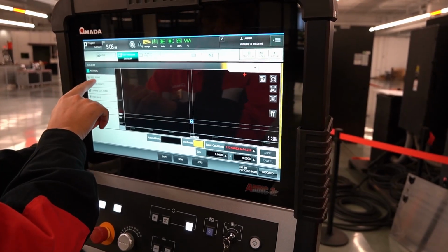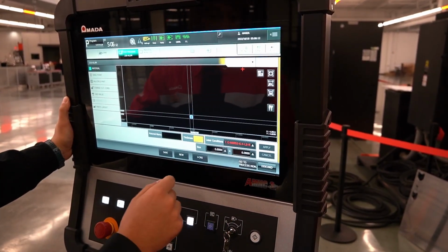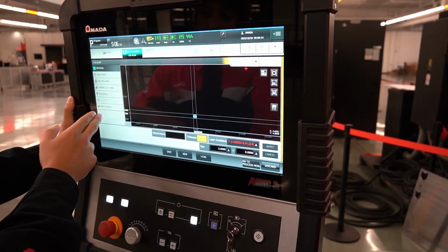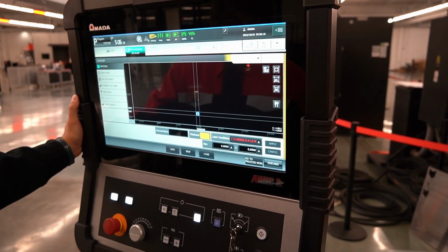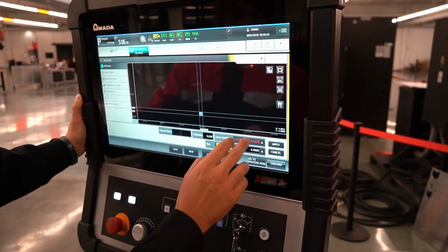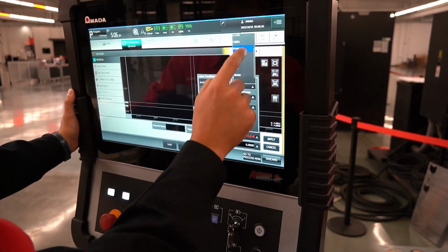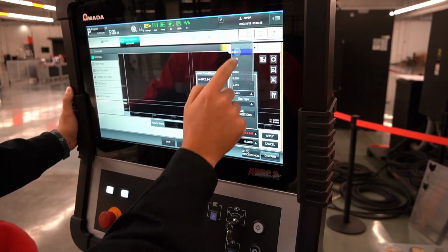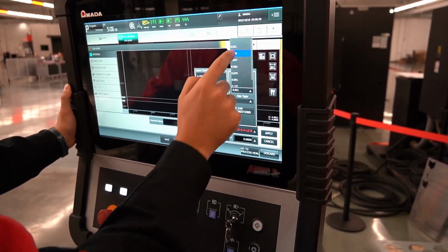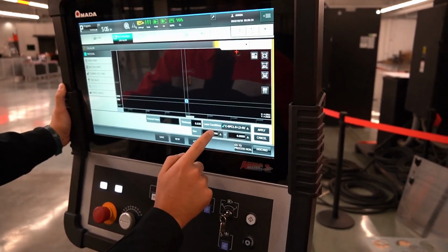the option to change cutting conditions. I'll go through all of them here, but change cutting conditions, nest, part layout. It's pretty cool. So we're gonna input our thickness here. I'm gonna choose my cutting condition for 20 gauge galvanized. Let's see, I believe it's 031, no, 039. Use my cutting condition here.